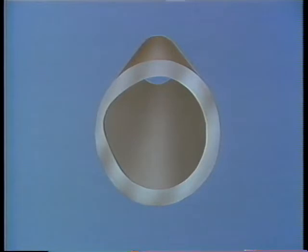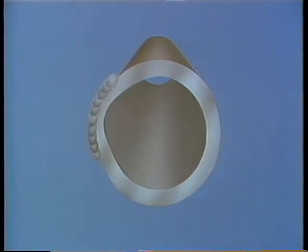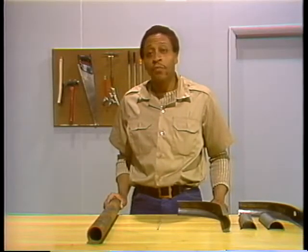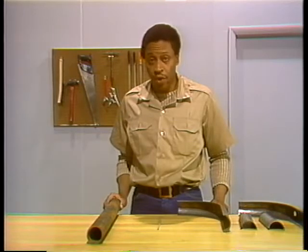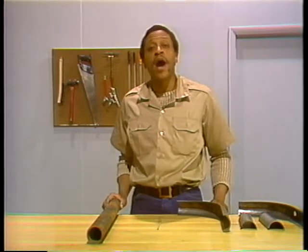Cladding is often used to repair localized tube thinning caused by corrosion and erosion. The thin area is covered with weld metal to strengthen it. This cladding helps hold the tube together and makes it less likely to fail. The additional metal added to the tube makes the damaged area more resistant to corrosion and erosion. Cladding may be used as a repair method whenever a tube requires reinforcement.